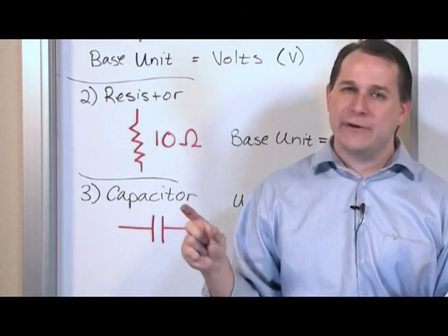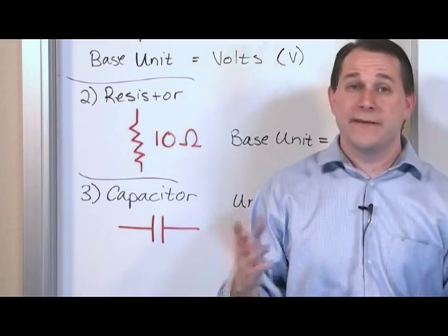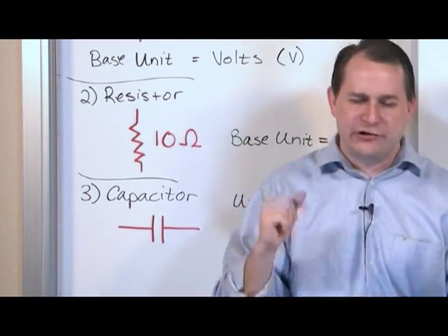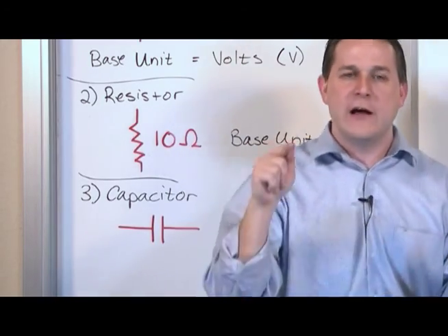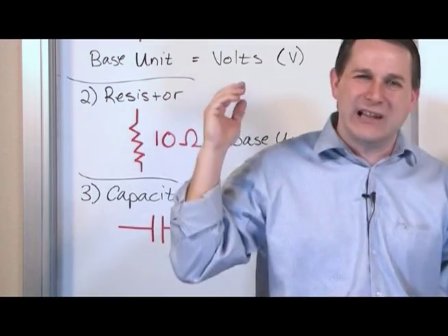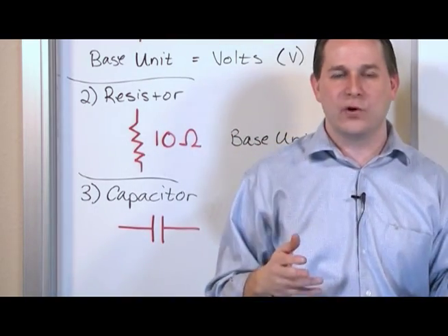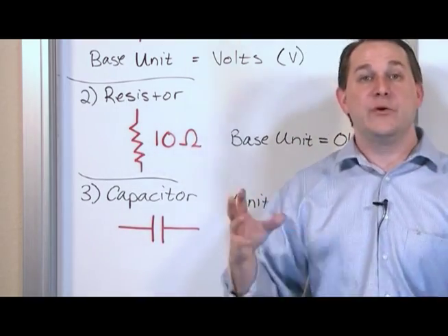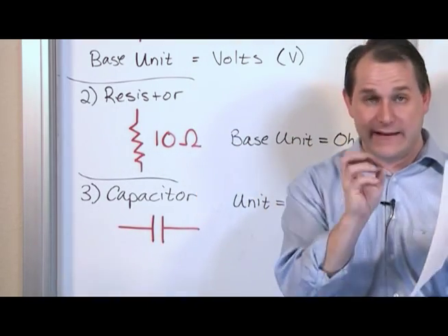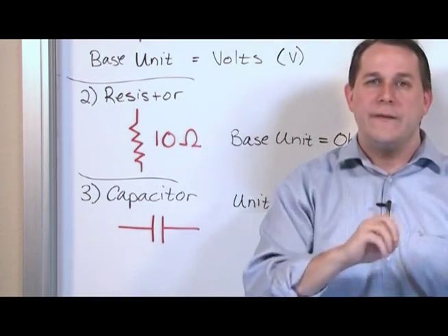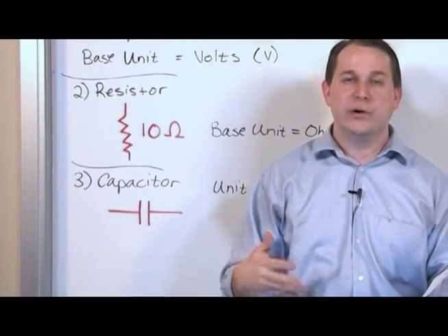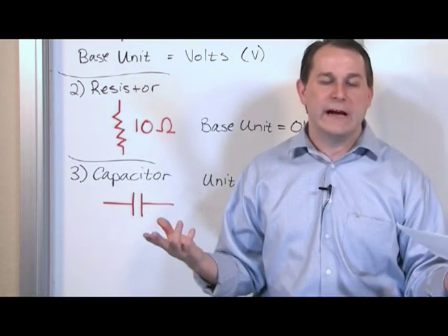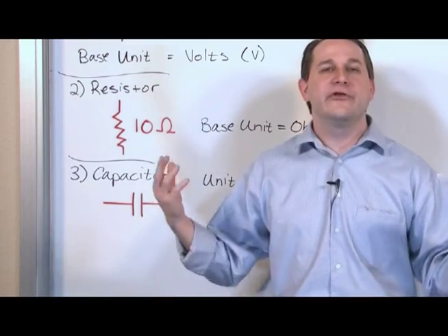So if you hook your battery directly up to the flash bulb, nothing will happen because there's not enough. You need it to happen like it's instant. It's like shuffling your feet across the carpet. You build up that charge and you touch the doorknob, and at that moment it's like a little lightning bolt went off and jumped across to the doorknob. Same thing for the flash. You've got to accumulate a lot of charge there and then release it all at once into the gas in the flash bulb, and then whammo, the gas releases a lot of light, and you can do it over and over and over again. This is probably one of the most intuitive ways you could think of when you would want to use a capacitor. So it's a storage device.